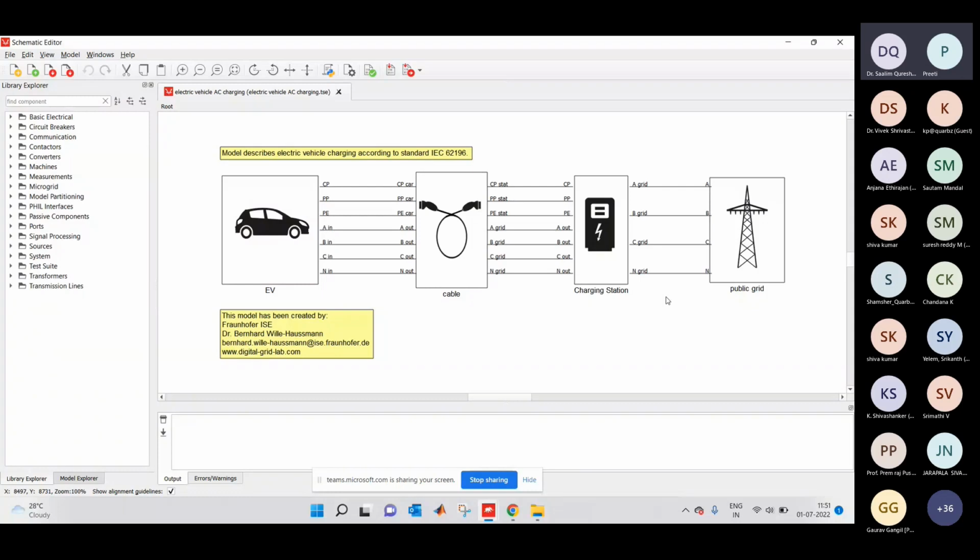To apply DC charging, significant information exchange between the battery and the external power supply is essential. Thus, high level communication is needed. But in the case of AC charging, just the pilot signal is necessary. Most stationary installed EVs apply mode 3, as it allows the highest flexibility and high charging powers. I will show you this in the application note that describes the procedure of signaling on the control pilot, CP, for AC charging according to IEC 62196 mode 3.